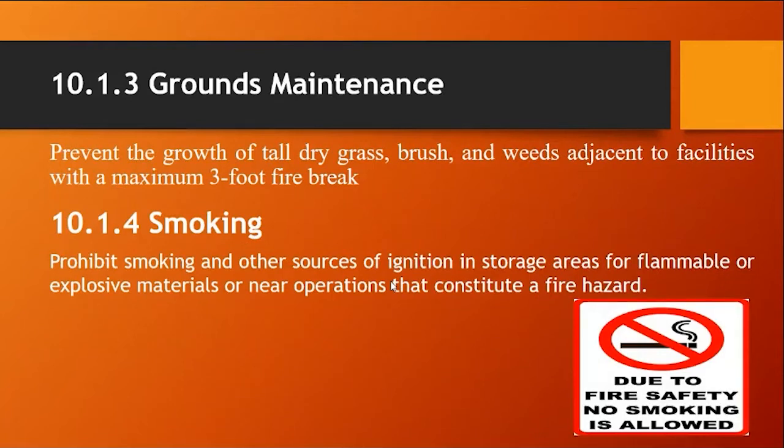Ground maintenance. Prevent the growth of tall, dark, dry grass, brush, and weeds adjacent to facilities with a maximum 3-foot fire break. Next is smoking. Prohibit smoking and other sources of ignition in storage areas for flammable or explosive materials or near operations that constitute a fire hazard.